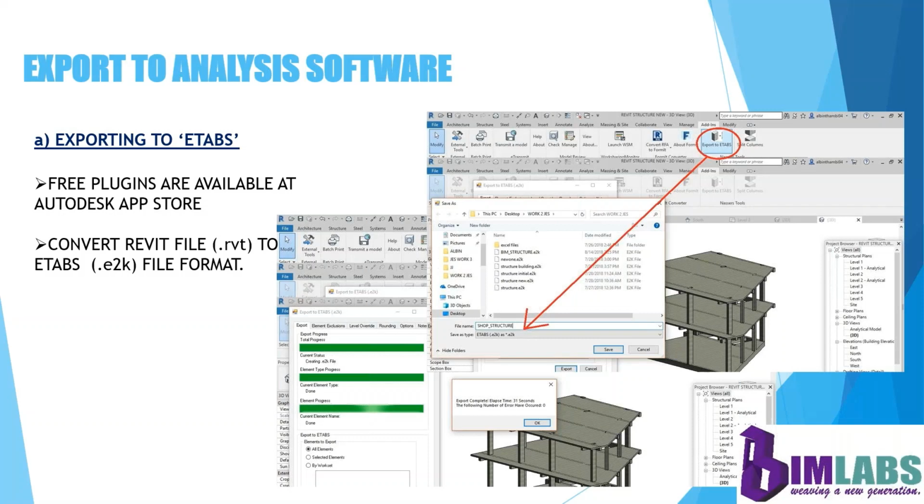So how to export it to ETABS? You are having a plugin called Export to ETABS. By that you can just export the structural model to ETABS by using this Export to ETABS. And another plugin is also there, CSiXRevit link. With that link, you can just export the model with the boundary conditions and loadings to ETABS. I'll show you that link once I open my Revit interface. All these plugins are available in the Autodesk App Store. Most of them are freely available. You can just use it.